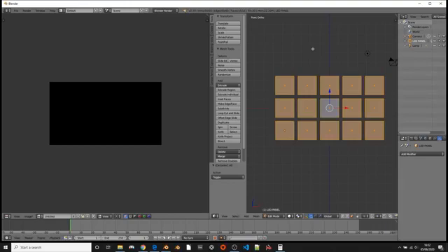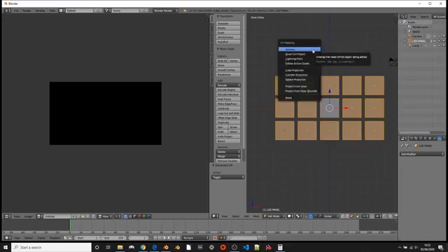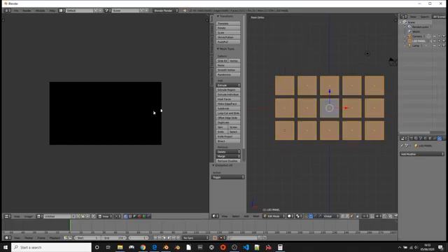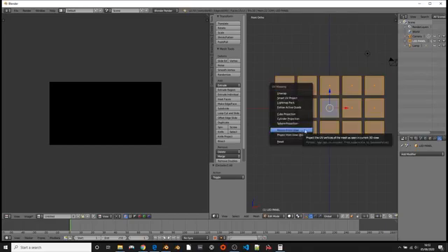What I'm now going to press is U for UV map. So that's U on the keyboard, U for umbrella. And it gives us this little pop-up here. Now I'm going to look at some of the other types in some of the other lessons, but what we are going to do, because I've chosen a layout that is going to pretty much fit in this texture area over here on the right, I'm going to use project from view. You've got 2 there, project from view and project from view bounds.